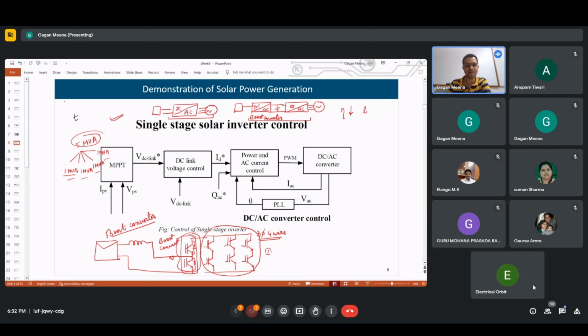And then capacity-oriented energy storages are the slow responding energy storages, and they can help in long-term energy balance or power balance. They can provide the tertiary frequency response, secondary frequency response, and also smoothen the output of renewable generators. All the other storages will come here: compressed air, pumped hydro. Now hydrogen is picking up, so the government has a lot of focus on hydrogen. So with this, both A and B were correct for this.